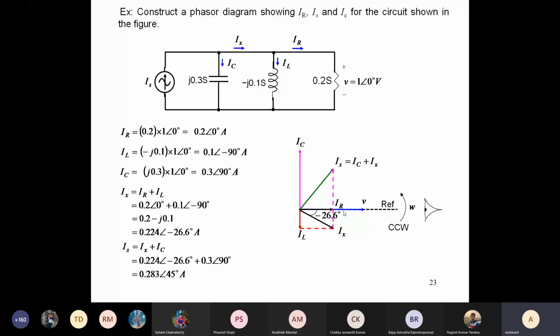Yes, sir. So then you don't even need to go to the fourth quadrant. All your work is done in the first quadrant only. Understood. So we'll find out the Ic minus Il phasor, then directly plot it. And that is again just a rectangle. Yeah, it may be easier to find out. Just applying tan inverse, you get the angle and all.